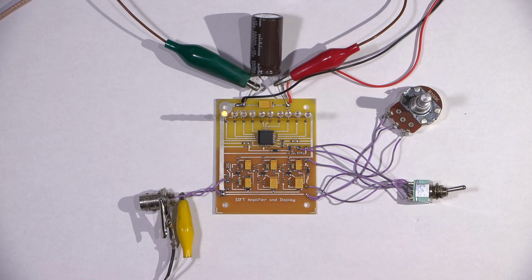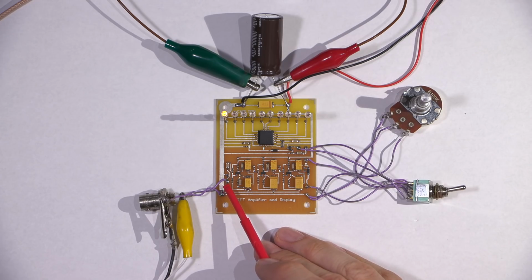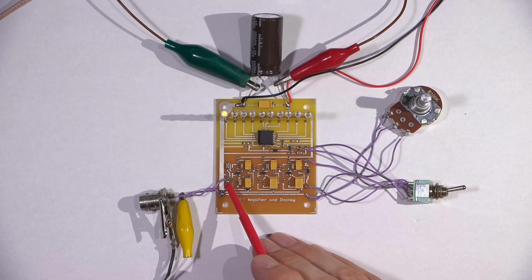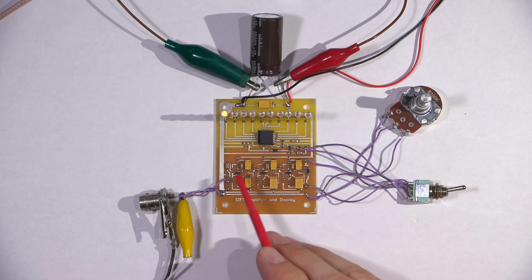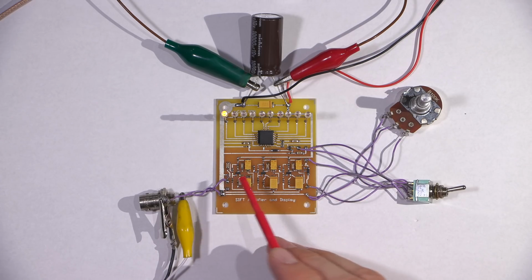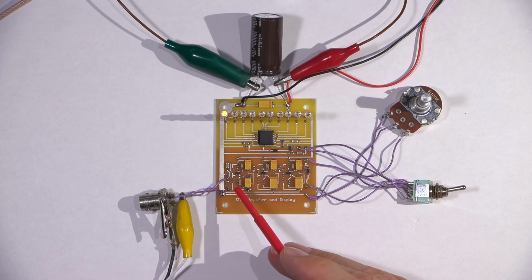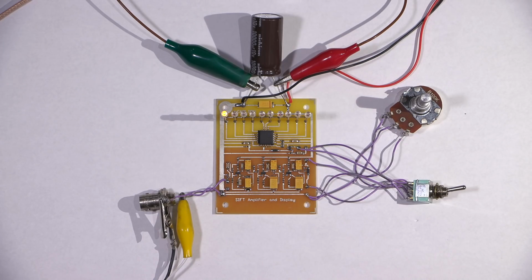But if you are ever looking for a low-level signal like this, what you usually do is go through the first amplifier stage on the device itself and look for the signal at that stage. If you can see an amplified signal over here, it gives you an idea that the first stage is working. That's a way you can kind of cheat if you don't have the test gear, and I've done it many times with older oscilloscopes. It works just fine. But it is nice to have that actual readout so you can trace those, basically sub-microvolt kind of signals, right? So a lot of really neat stuff coming here.